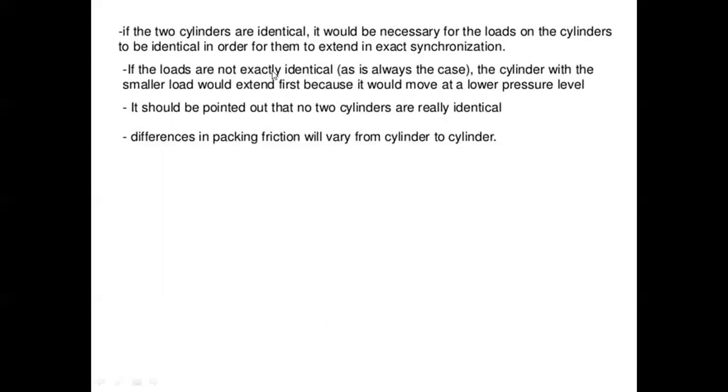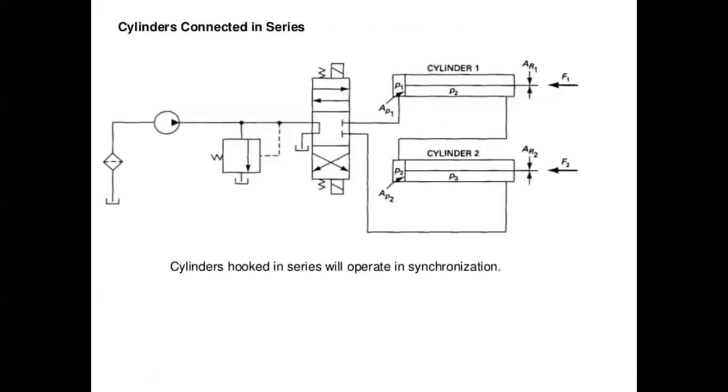If the loads are not exactly identical, the cylinder with the smaller load would extend first because it would move at a lower pressure level. It should be pointed out that no two cylinders are really identical. Differences in packing friction will vary from cylinder to cylinder.